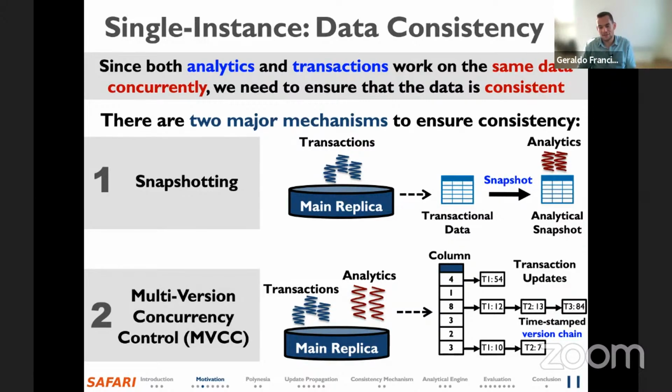So the mechanism would need either a software approach or some way to make sure that the placement of the data is well laid out inside the memory for the analytical replica, so that we can do this copy from one place to the other nicely. But definitely that could be possible, and probably would even provide higher throughput than our copy unit, because the throughput of subarray copying of RowClone is quite high. Yeah, and also save area, right? And save the area in the logic layer.